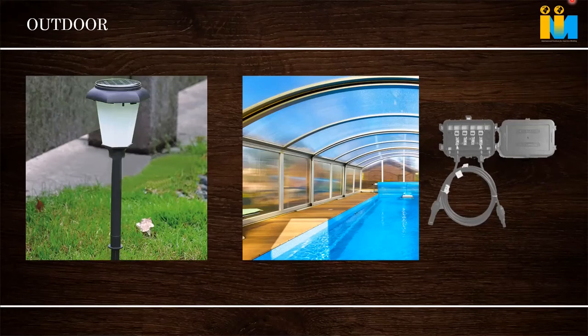After that weathering, what they will be checking is whether this part has shifted its color, whether the mechanical property has changed, what the electrical property is before and after, and what the thermal property is before and after. We'll be comparing all the things and coming to the table. Generally, safety factor is more important than color, but many end customers see just the color. They feel that with a color shift, the property has changed.